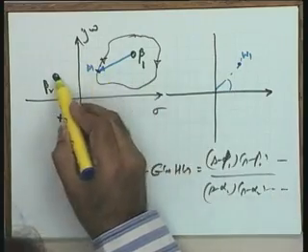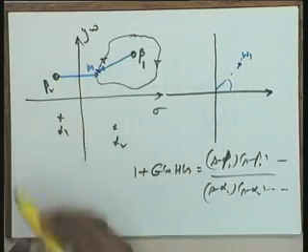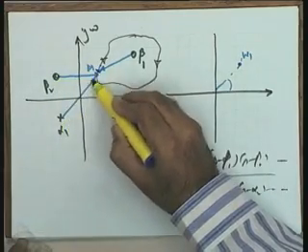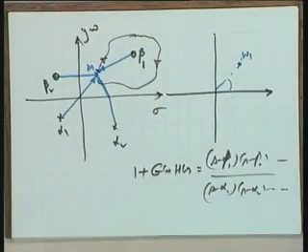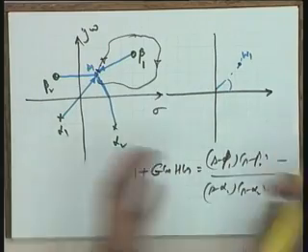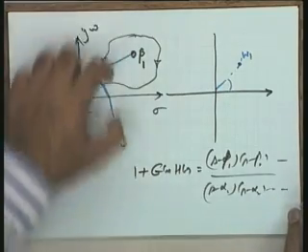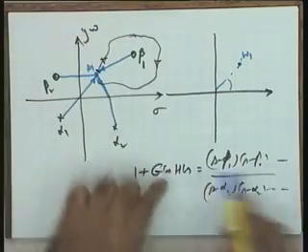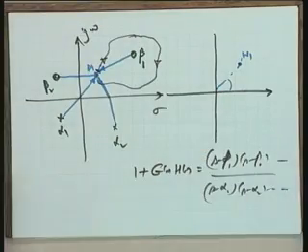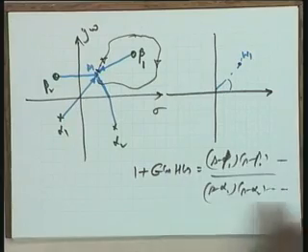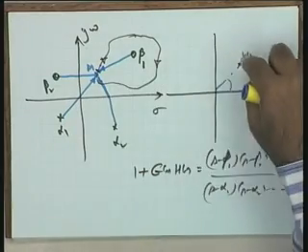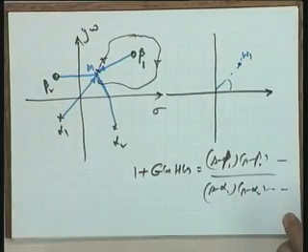Similarly, this is the S1 minus beta 2 phasor, this is the S1 minus alpha 1 phasor, this is the S1 minus alpha 2 phasor and so on. Since graphically you are working with a graph, you need not do the calculations, you just measure all these phasors, multiply the numerator phasors, multiply the denominator phasors, divide, and that gives you the magnitude. The numerator angles minus the denominator angles gives you this angle, and hence there is a corresponding point.